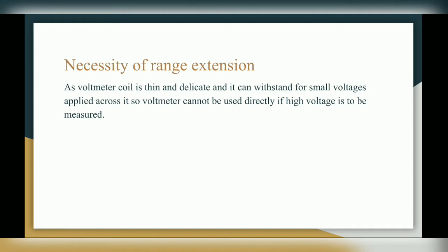So first, necessity of range extension. Why do we need to extend the range of voltmeter? As the voltmeter coil is thin and delicate and can withstand only small voltages applied across it, the voltmeter cannot be used directly if high voltage is to be measured. So to measure high voltage, we have to extend the range of the meter.